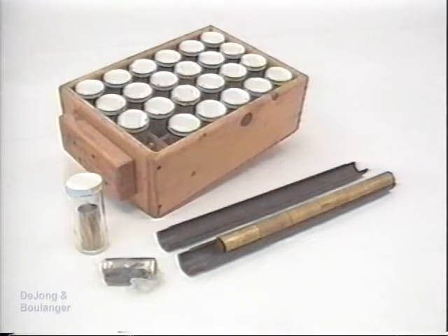After the sampler is withdrawn from the borehole, the engineer disassembles the split spoon and inspects and classifies the material. The sample is then stored, such as in a sealed glass jar, and shipped to the lab for testing. If the split spoon contains 2 or more distinct soil types, each soil type should be stored separately, or they may get intermixed and subsequently misclassified in the lab.